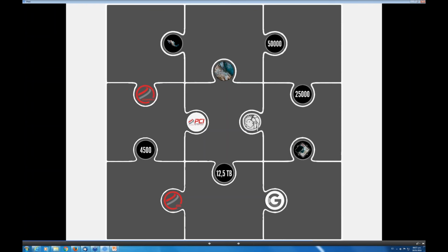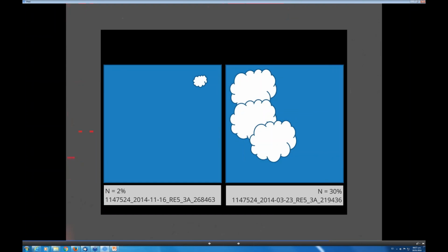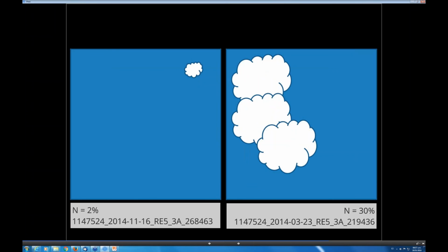Basically, the Smart Geofill tool allows subsequently adding scenes to a mosaic already generated. So let's think, for example, here we have our best scene with a cloud coverage of 2%. As this is the best scene available, we will use it for the first version of the mosaic. Now I have here this little cloud disturbing my mosaic. So let us further imagine that I have a second scene for the same place with cloud coverage of 30%, but just where this little cloud is disturbing my best scene, the second best scene with 30% cloud coverage is completely cloudless here.